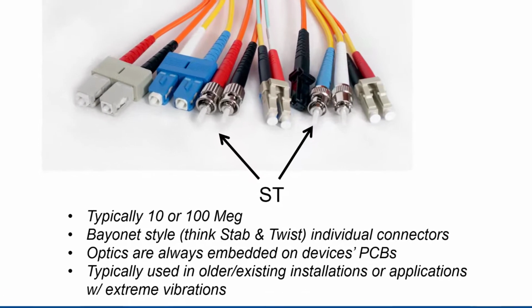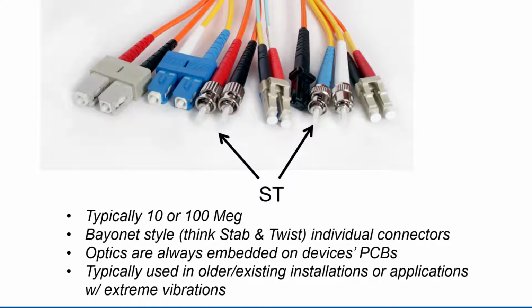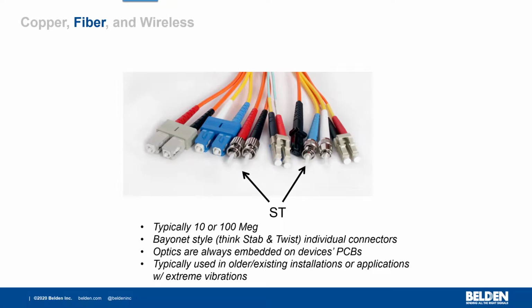Next, we have the STs. These are typically thought of as the stab and twist. It's a bayonet style connector. These are predominantly utilized in legacy installations or installations with extreme vibration and or shock. Here too, the optics are almost always embedded on the device's PCBs.